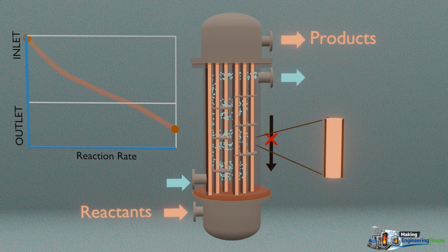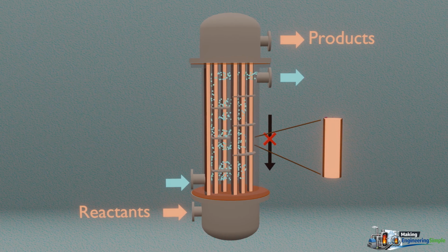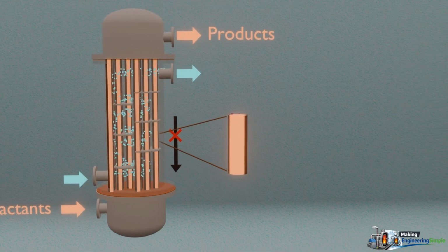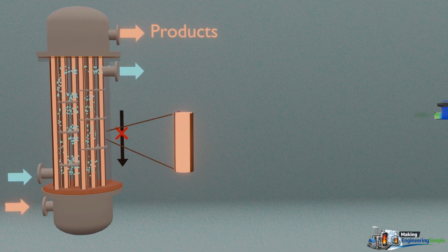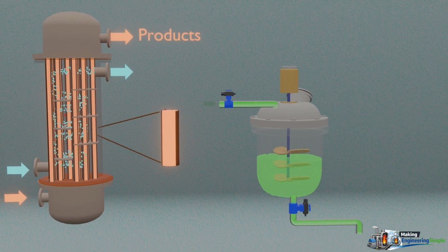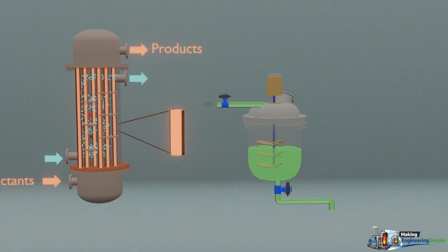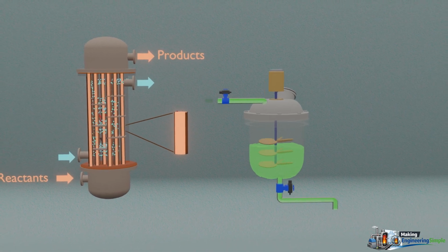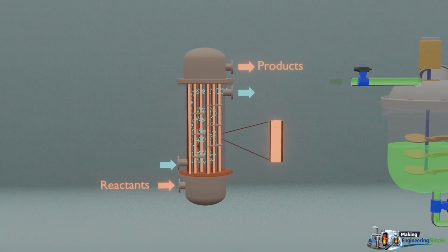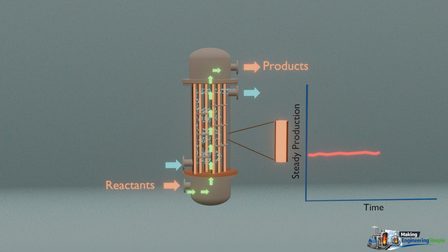The lack of back mixing is the PFR's biggest strength because fresh reactants never get diluted in the way that it does in a CSTR. The average concentration through the reactor is high, which means faster reaction rates and higher conversion for a given volume. For the same job, a plug flow reactor is typically smaller than an equivalent CSTR. It's also continuous, so you get the steady ongoing production a CSTR also offers.